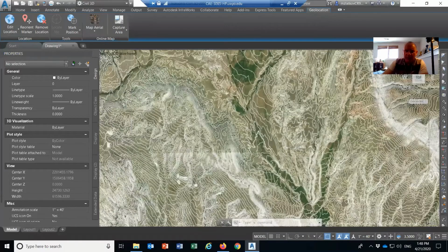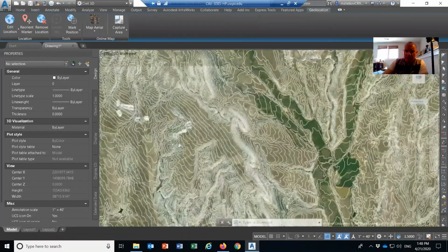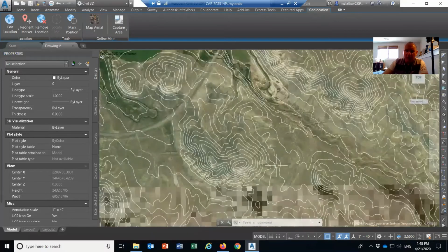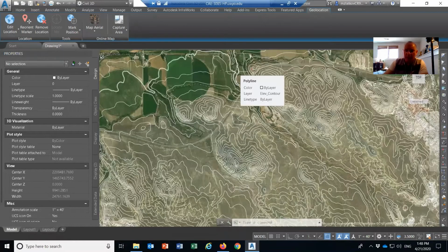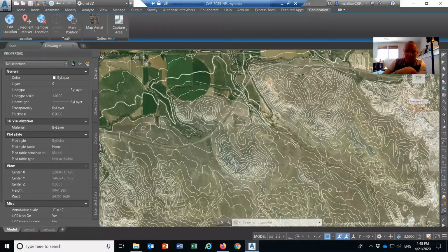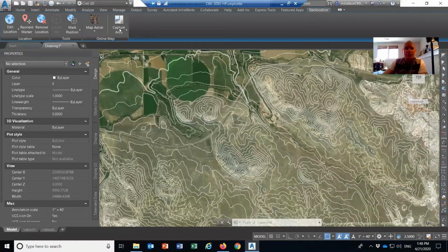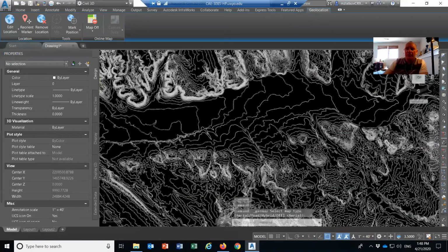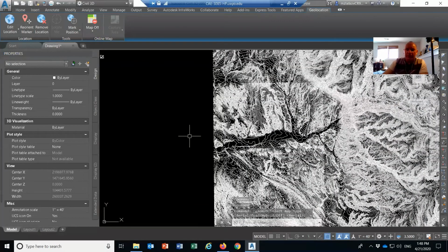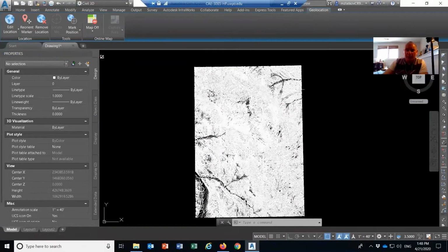The road I'm going to be developing will have a starting point somewhere here underneath this crop circle, and then I need to go down to Highway 14. Sorry, the problem I'm having is that I'm connected remotely, so my mouse is a little bit oversensitive. I need to connect that to this roadway here. I'm going to show you that later. For now, I'm just going to turn it off. This is another good check: make sure that your aerial map corresponds to the contour lines that we have in here. Otherwise, if your map doesn't turn on, it means you have a problem with the coordinate system.